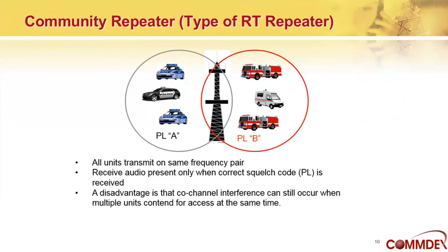And as we said before, the disadvantage is they're still out there. The other people are still out there. So in order to use this type of system, you have to disable the squelch code on your receiver so that you can hear if there's any activity before you talk. And if there is no activity, then you can go ahead and talk. So it can be a little bit of a nuisance. They call that the monitor function when you just your receive PL prior to transmitting. So just like anything, listen before you talk.